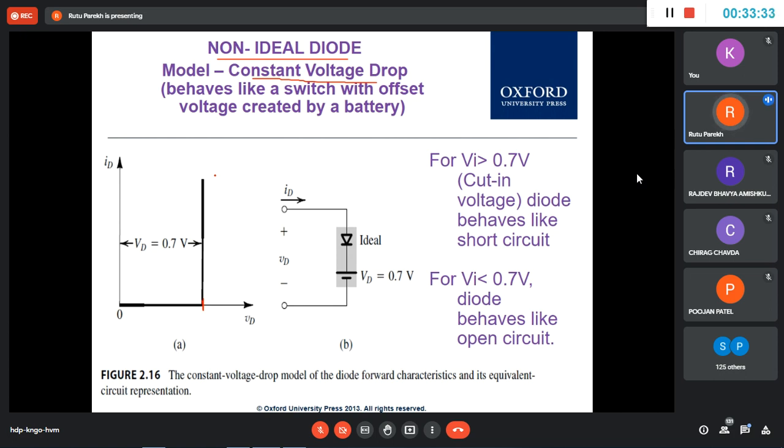So now if you want to use it in your simulation, then it will be replaced, and this is equal to, this is an ideal diode, starts conducting at 0 volt. Okay, and this is the potential 0.7. So only if this potential positive is more than 0.7, it will conduct, otherwise it will not conduct. Okay, and why here are we keeping an ideal diode? This is a diode model, and to show the direction of the current. Okay, it starts conducting at 0 volt, but we keep this symbol to show the polarity, the direction of the current. We will show with this because it's a device which has a direction of the current. So this model is equal to ideal diode plus the supply.